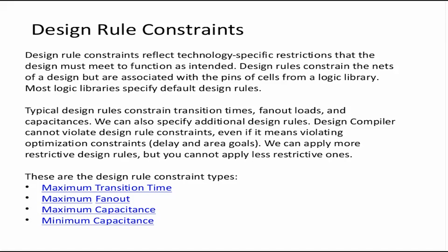Typical design rules constrain transition time, fan out loads, and capacitance. Additional design rules can also be specified. DC will not violate these, even if it means violating the delay and area goals. We can apply more restrictive constraints than the limits in the library, but less restrictive constraints cannot be applied.